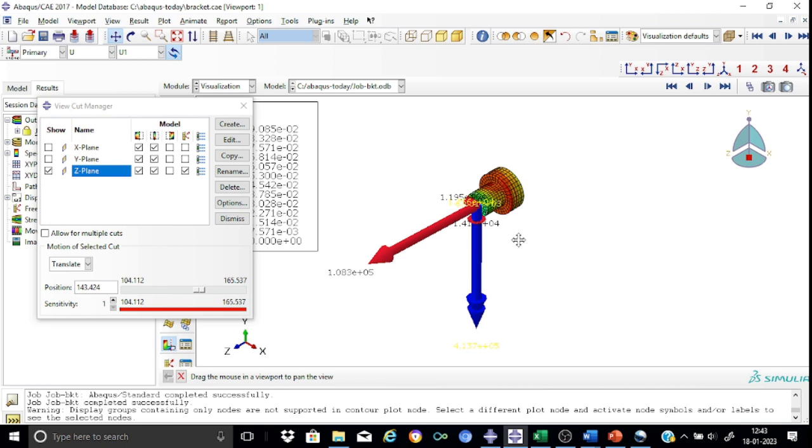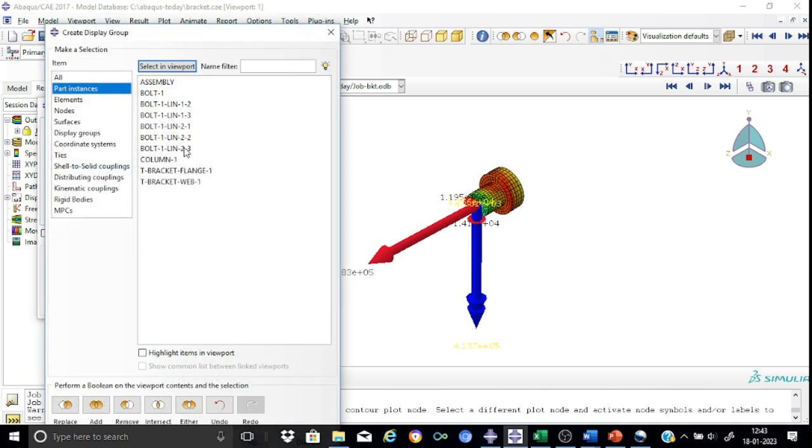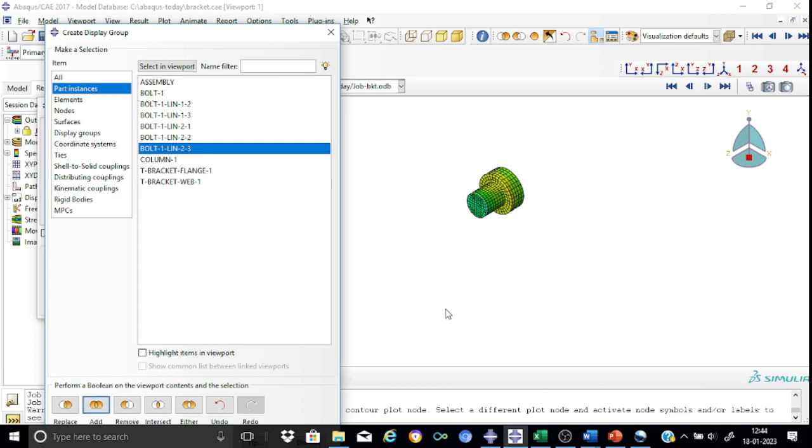This way you can also see the variation of the bolt force for the various time frames. So this is all regarding the top bolt. Note down the maximum force in the top bolt, that's around 110 kilonewton. Now we can also select one bottommost bolt. For that, we can include one. So this should be the bolt, probably in the bottommost row.